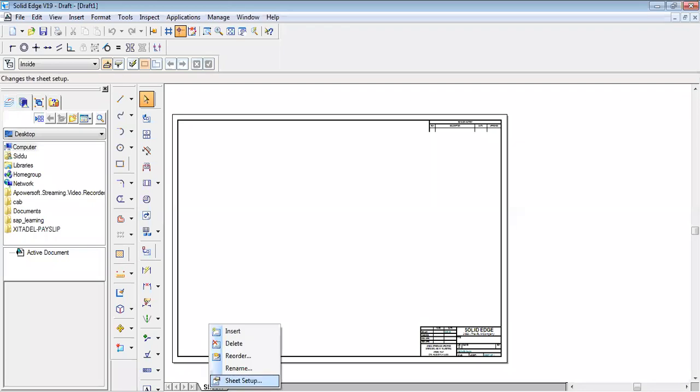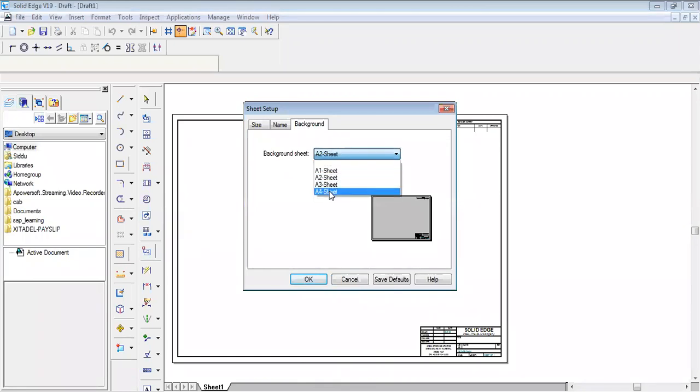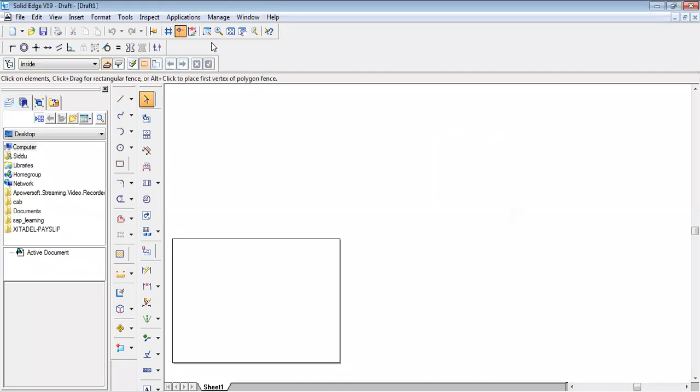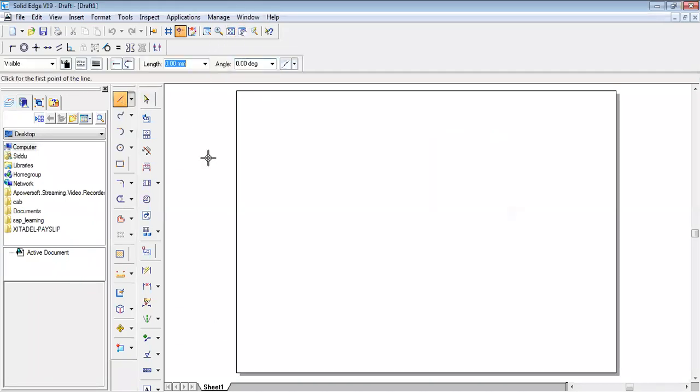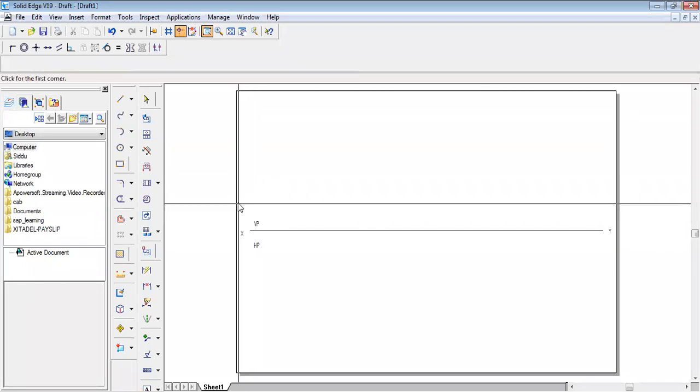Select the drawing sheet, make it A4 in the background as you did earlier. With that, the sheet is ready to use. So draw a normal line with a thickness of 0.35, only for the XY line we do that. So just say X, and here is my Y, vertical plane and horizontal plane. Now zoom in on everything and then do it.